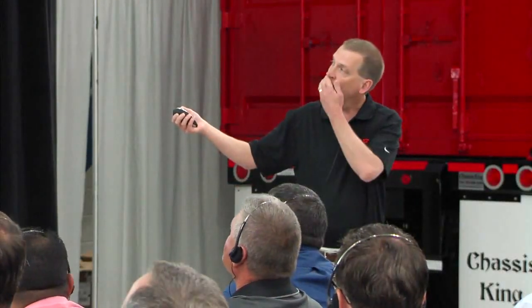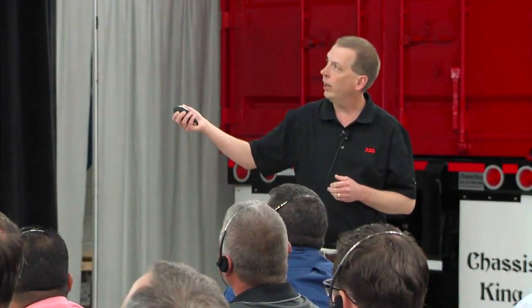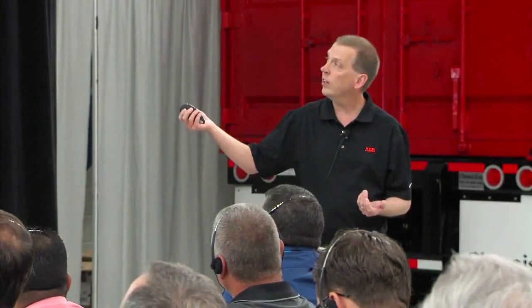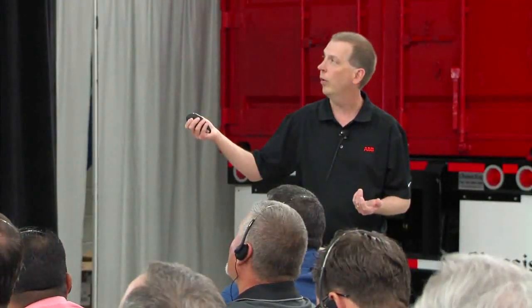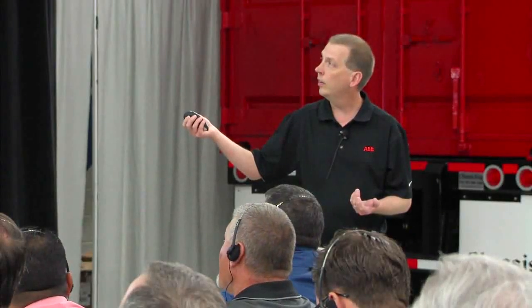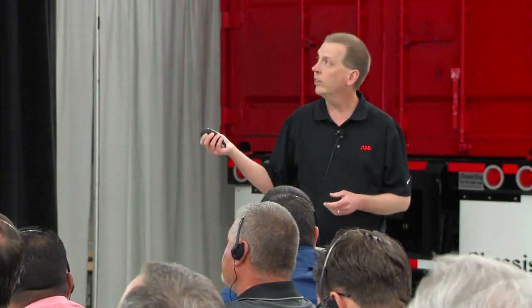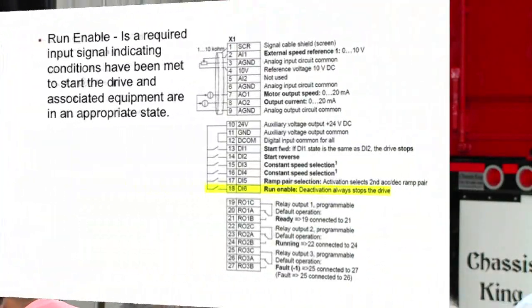A lot of times, interlock contacts are brought in here into the stop command so that the drive will stop if any kind of safety switch is open. That's why they're always normally closed. And the reason that stop buttons are really normally closed is this simple. If a wire falls off, the drive is going to stop. Any kind of loose wire, somebody yanks on a cable, it's going to stop. That's safe. If the drive kept going when somebody pulled a wire off the stop button and I couldn't stop it, that would be a problem. So the reason the stop button's normally closed is for safety.